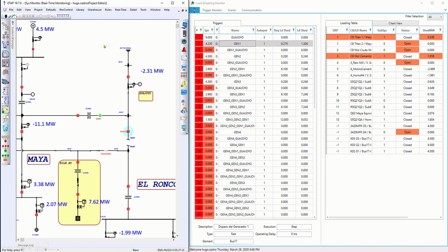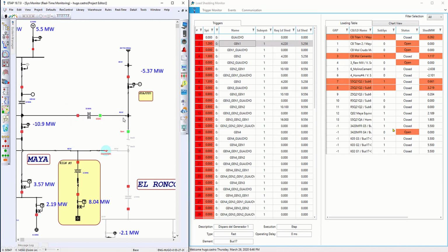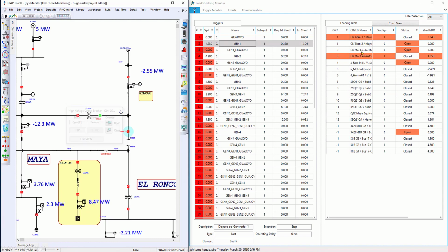This trip is not only looking at the topology, the connectivity of the system, but also the operating generation and load levels. So you're no longer left with a static priority table, but through every contingency, we are generating a dynamic priority table that meets the stability requirement of the system. And that's key. It's not just looking at the delta of power generation and load as an algebraic equation, but it's looking at the dynamics of the system to understand what loads need to be shed that are non-priority loads